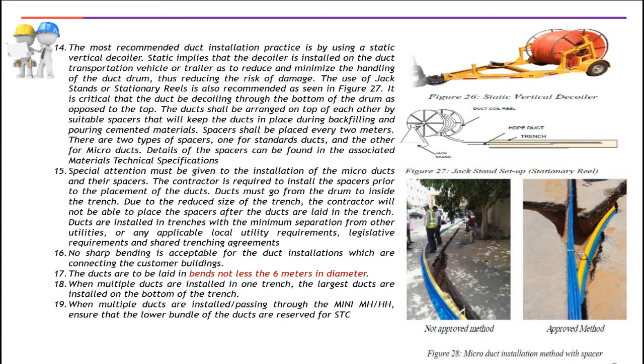Ducts shall be properly arranged on top of each other by suitable spacers. Remember that there is a spacer intended only for standard and micro ducts. Always install the main ducts first at the bottom of the trench, followed by the drop ducts.